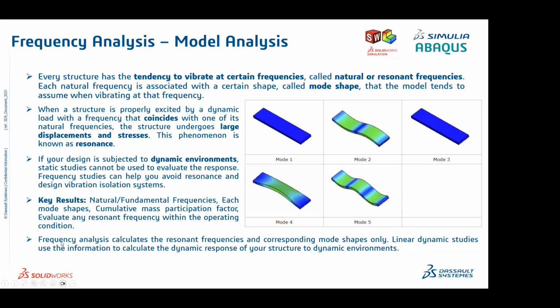Okay. So frequency analysis calculates the resonant frequency and corresponding mode shape, as I told, and a linear dynamic study uses this information to calculate the dynamic response. So for any dynamic simulation, the base fundamental analysis you have to perform is a frequency analysis without any loading condition. How the structure is going to behave, you need to evaluate before any dynamic simulation.